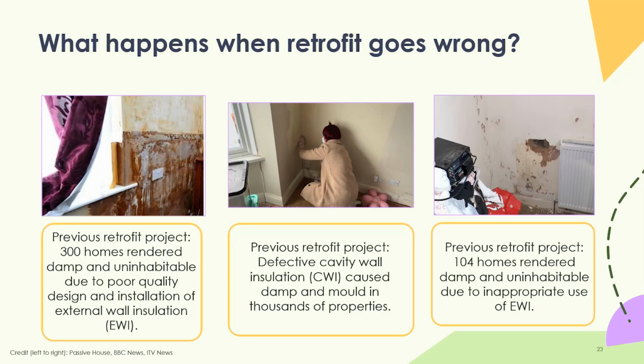What happens when it goes wrong? This is why we have PAS. There are some examples here of what happens. There's an example of 300 homes that were rendered damp and uninhabitable due to poor quality design and installation of EWI. You can see there what's happened.